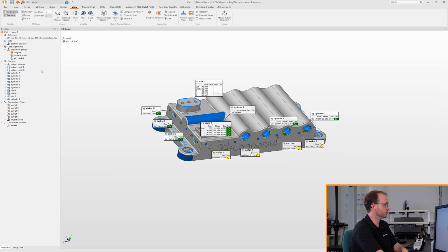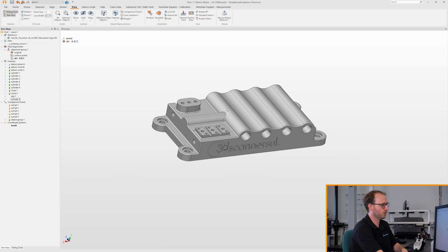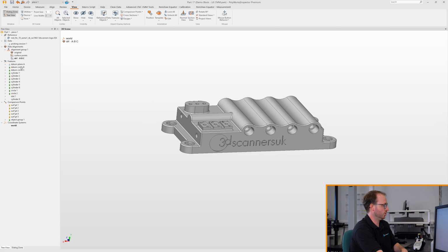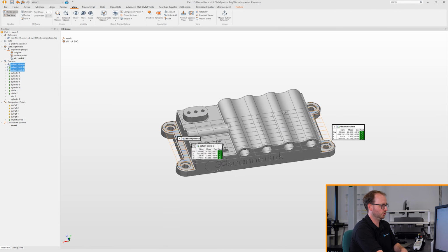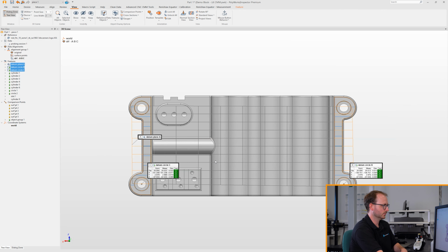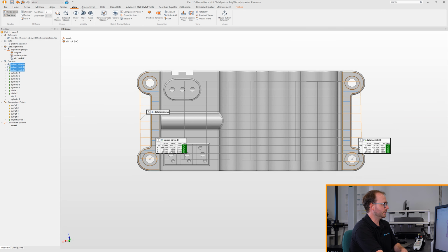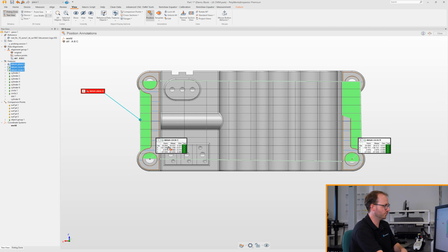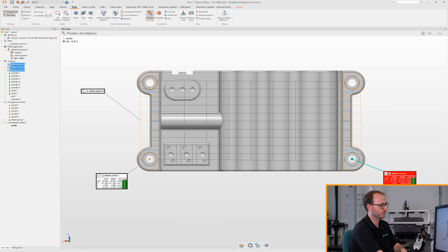What I will do first is indicate the CAD, and I'm going to show the datums initially. Now in 2024 and 25, I can highlight our features, right click, and go to show. Then I can position our model so I can see those. I can use our coordinate system in the bottom left corner and zoom out a little bit more. Again, in our view tab, we have our position tool. So I can click on the features, move them where I need them, then right click to come back out of that.